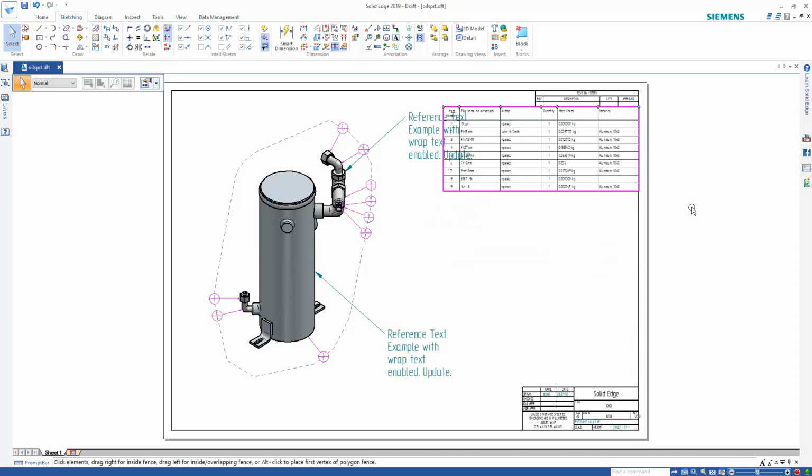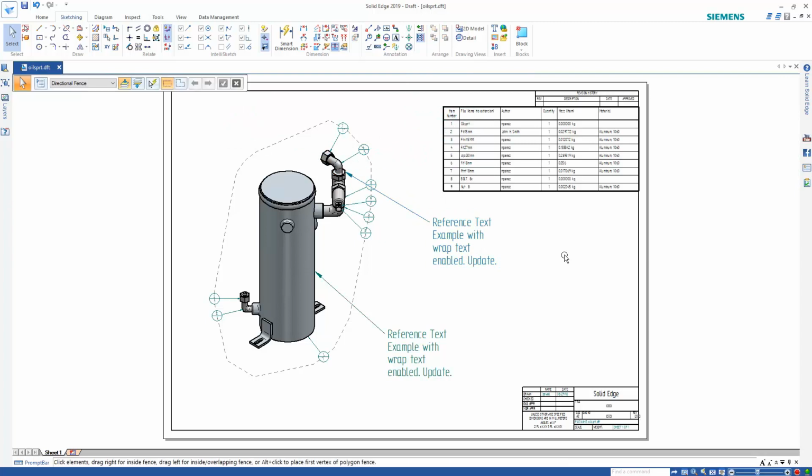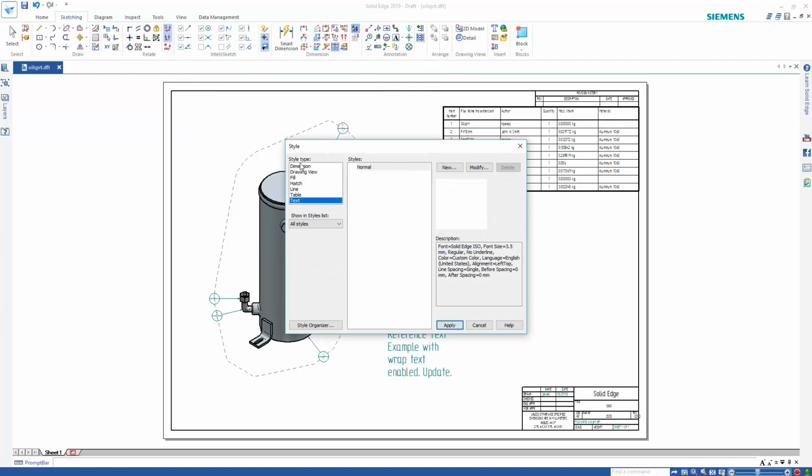I also want to change some of the parts list formatting, but I haven't been able to find the option I need in table properties. What I want to do is make the outline colour light blue. And this is because usually such options aren't directly controlled by properties but by styles, because they're to do with aesthetic appearance and not how data is displayed. Such options are usually set up in your templates.